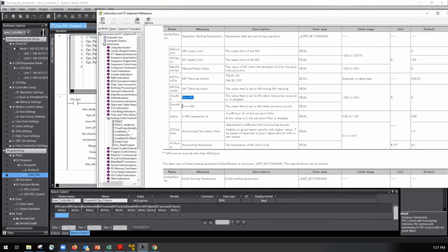Next one we'll look at is error MV. If there's ever an error in the function block, the input goes beyond the scaling range, or something happens outside of the block that gives a bad value on something, we can actually have this fail to a certain value. This is something that I used to use in the water wastewater world when I was doing integration.